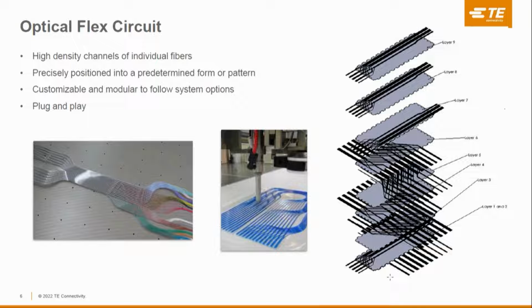The way we make this optical flex, we've developed fully automated systems to be able to run this into production. We are able to lay individual fibers one by one in a very already defined footprint and route those fibers from the input area where we want the fiber to come in to the output coming at the right location within the processor system and the footprint.